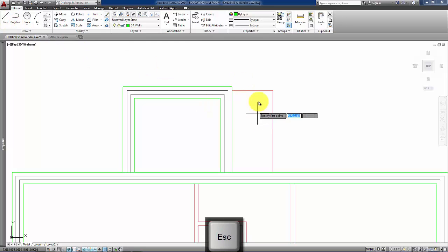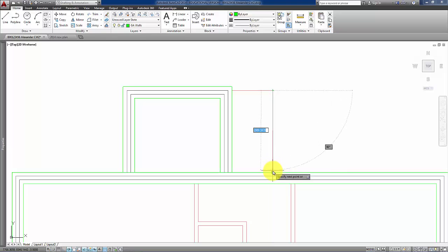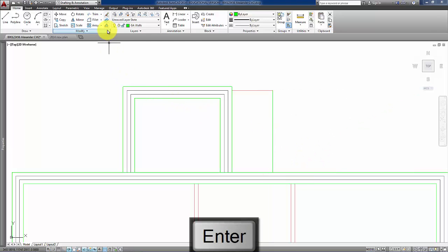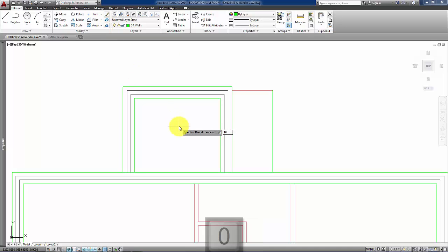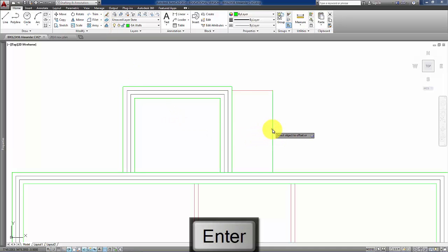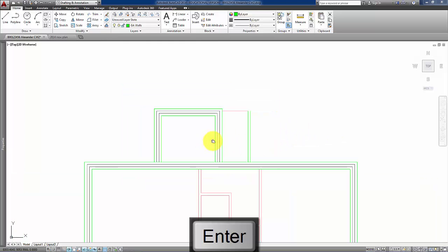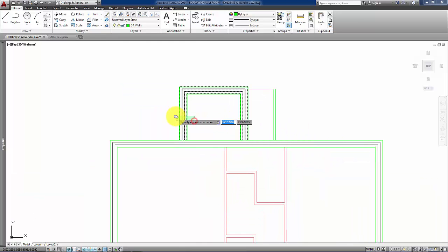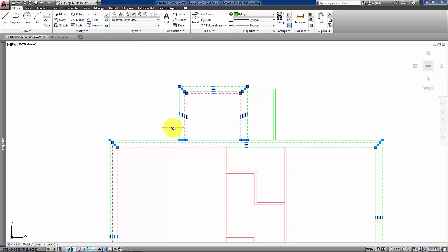We need another line over on the right hand side here just to pick up the line for the boiler room, and we can offset that by 100. At this point then, the two sets of polylines we can select and explode. Make sure that your room layout layer is locked, otherwise those will be exploded as well, but because they're locked, in this case they're left alone.